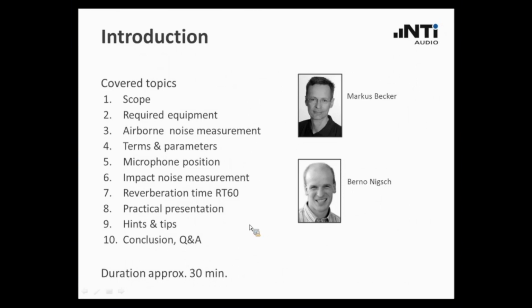Here you see a list of the topics that we have prepared for you. We will say some words about the required equipment, about airborne and impact noise measurements. We will clarify some terms and parameters and the issue of the microphone positioning. We have a brief statement about the reverberation time measurement, which is also part of this whole procedure.